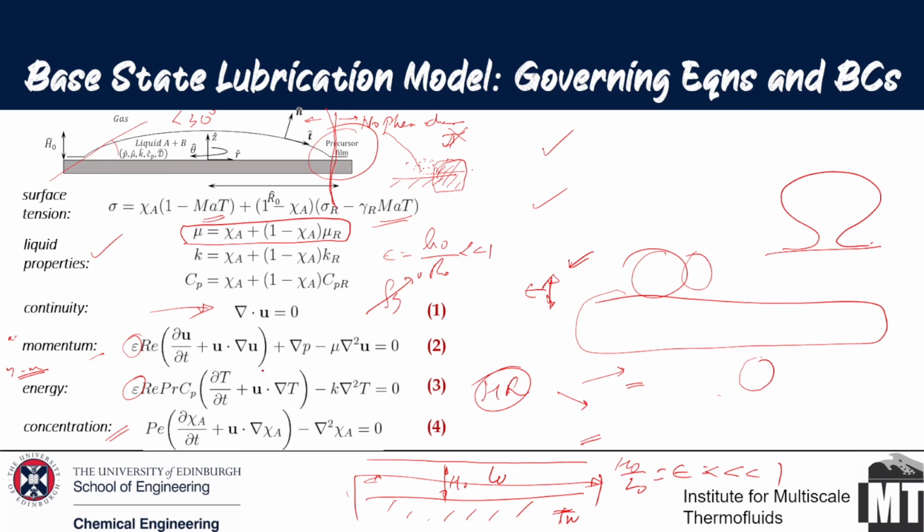You can't neglect it. Epsilon could probably be greater than 1. So you will have more effect of inertia in the droplet, and that can cause currents inside the droplet. If you want to go for hydrophobic systems, we can't use lubrication modeling at all.